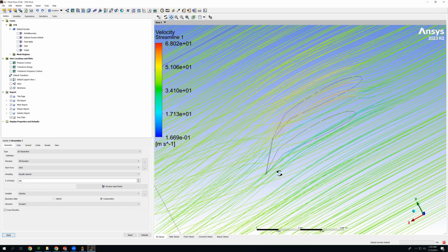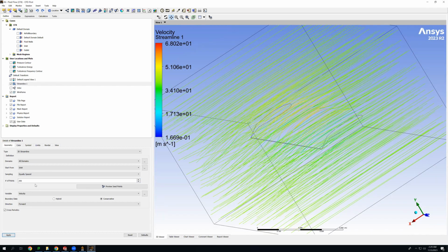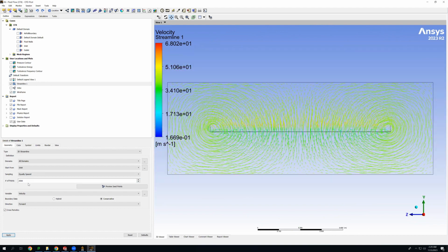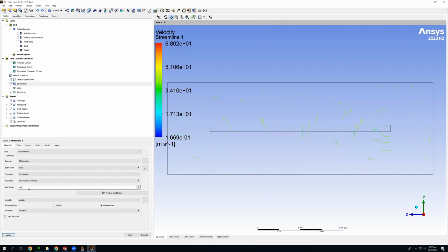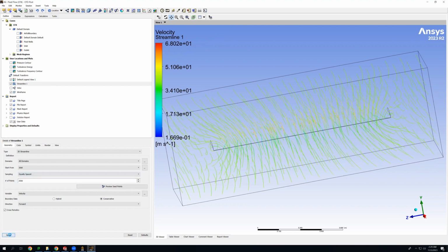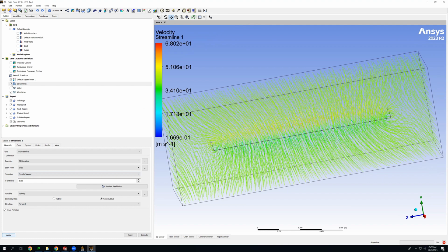And here you can see a similar pattern with orange lines going above the airfoil and bluer lines curving below it. I'm going to increase the resolution by adding more lines. And you can generally see that same path and a similar spiraling motion here with the 3D streamlines. You can also set it to skew as face center, and this generates more of the lines near the center. But I'm going to go back to the equally spaced one and save that.